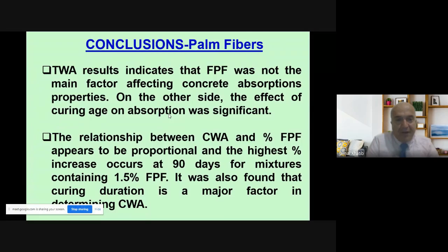Although you compact them very well, inside it's very difficult to assess whether they are compacted properly. On the surface, they appear okay. So maybe that's why we're keen to do some SEM studies on different surfaces to compare. And again, in here, there is obviously no straightforward relationship or correlation between capillary water absorption and the amount of fiber used.